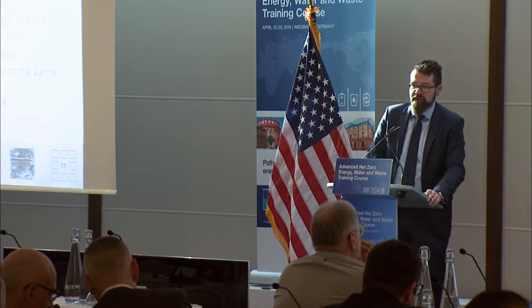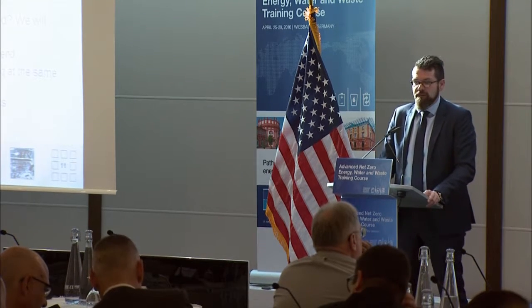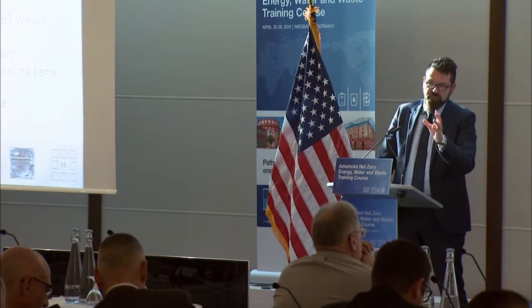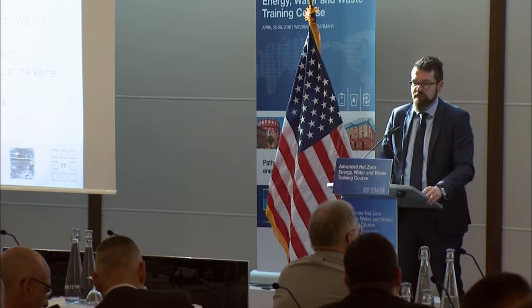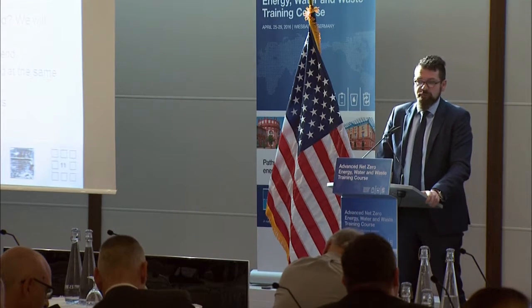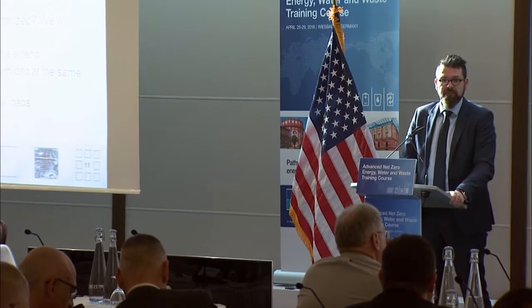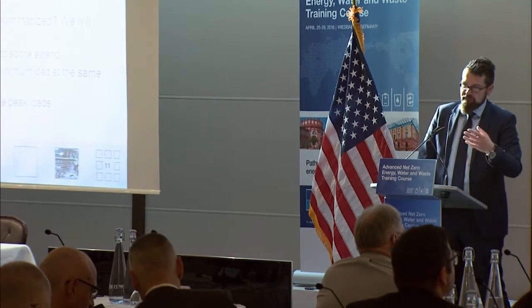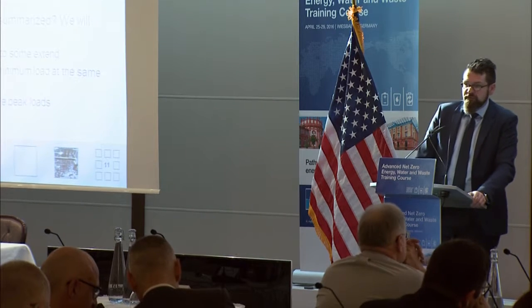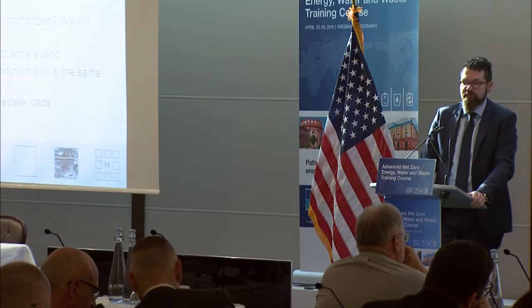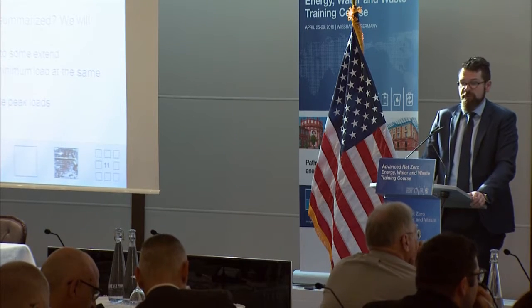The interesting thing is now, if you overlay them, you can see on the left-hand side the red curves. We have the different peaks, the different shapes and the shifts from zero all through the day. If we summarize them, we end up with a curve which has a slightly different shape. You can still see the peaks, but they are not that high. And what happens if you summarize them? You will have a factor of coincidence. So peaks and low marks will balance out each other to a certain extent.